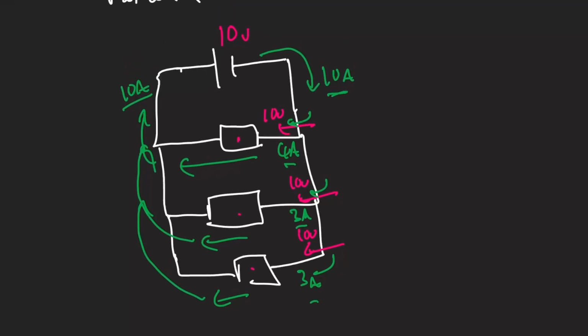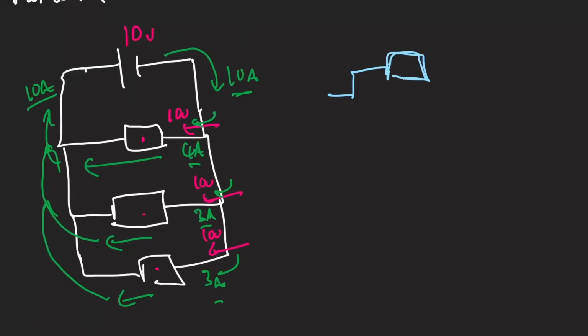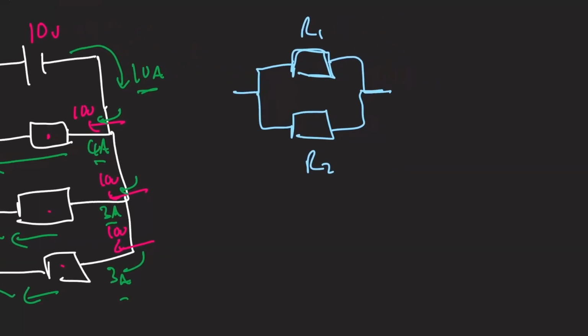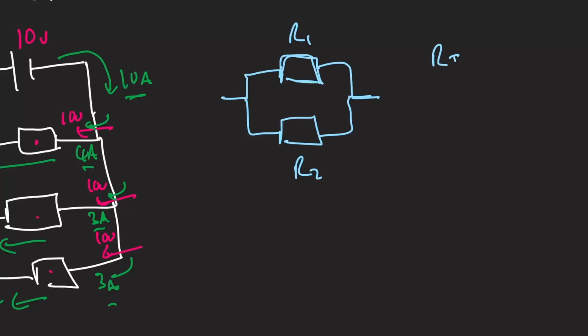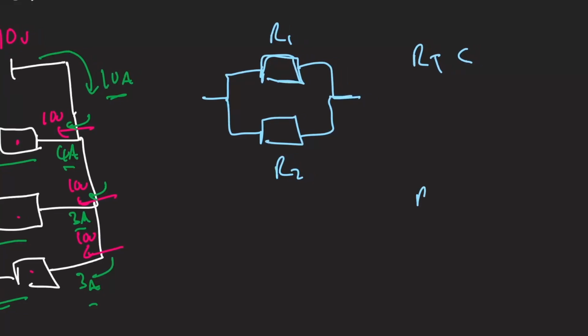And so the last thing we need to look at then is resistance. So when you set up resistors in parallel, that might look something like this. And the idea is that these individual resistances will have R1 and R2, right? So you have different resistances for each component. And the idea here is we're not going to have an exact formula that we need to know to work out the total resistance, if we were to combine both of these, but the total resistance would basically be less than the smallest resistance, okay? So in this case, if we say R2 is smaller than R1, so R2 is the smallest resistance, then RT would be smaller than R2 as well, okay? So it would be smaller than R2, which is smaller than R1, right?